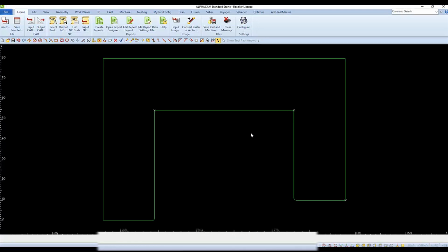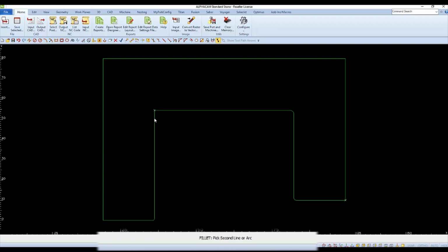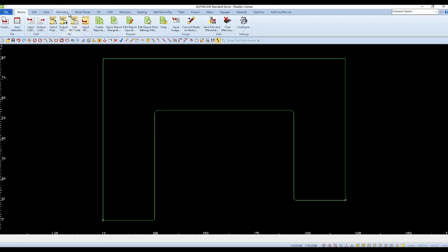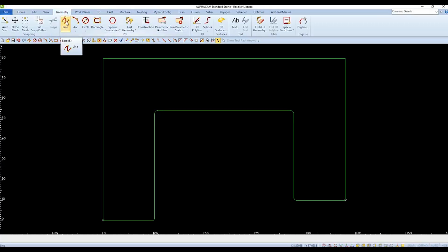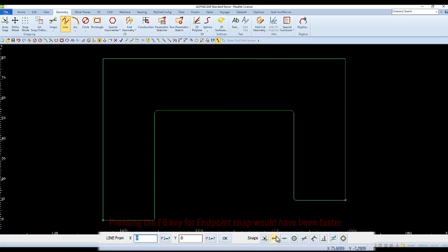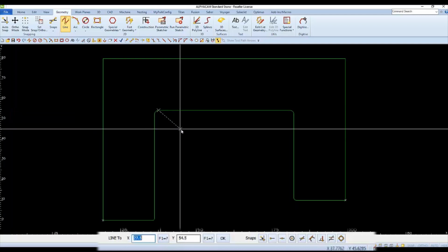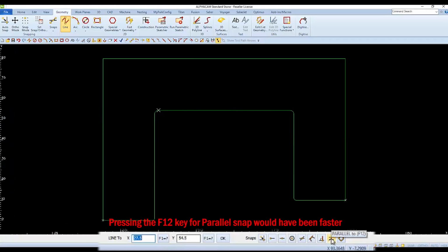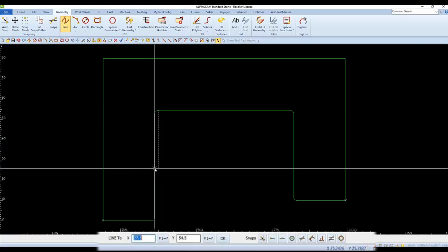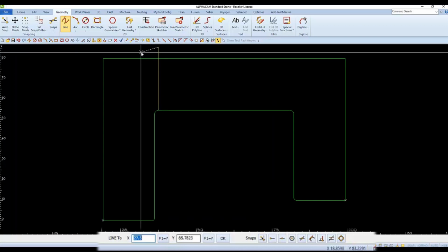And now we can add fillets to the inside corners with the 2-inch radius. We'll draw a straight seam using a line. Choose a line, and then we'll start at the end of the inside corner. And we want the line to be parallel to this front edge. So we'll select it and then bring the line all the way back past the back edge and right-click to